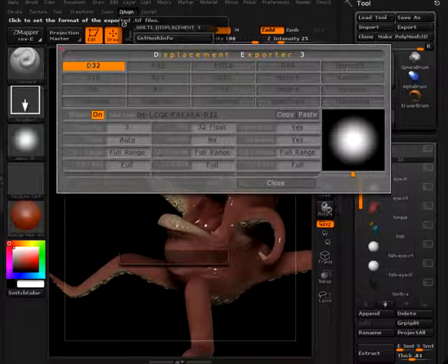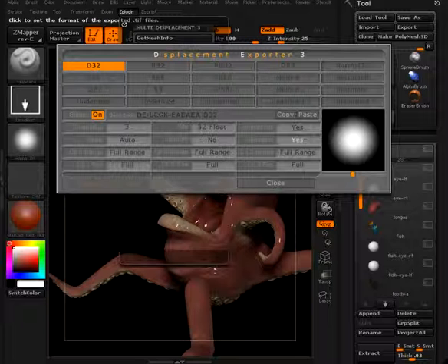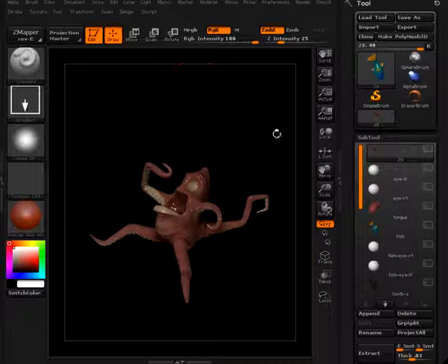So right now I've got D32 displacement, 32-bit, and I've got the status as on. None of these others are turned on, but it will allow you to create multiple maps at the same time. So for mine, I've got 3-channel, the scale is set to auto, and I've got full range on channels 1, 2, and 3, and I've also got vertical flip set to yes. All right, so once we've got those settings defined, we can now export our displacement map.